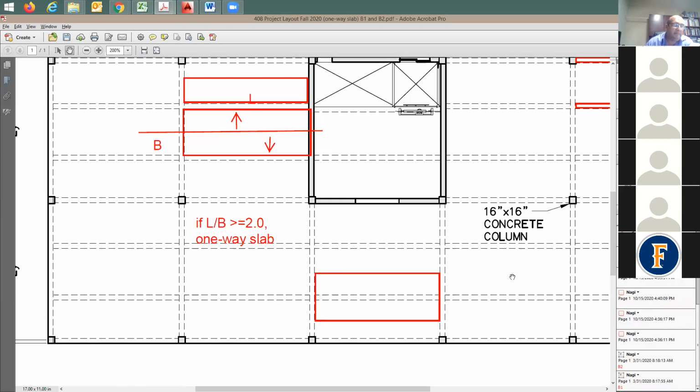If you'd like to design the beam and you need to figure out how much load goes to this beam, you need to find out the weight, as in dead load and live load that you guys have seen before, supported by this beam. Find out this area, multiply by the uniform load, to find out the total load supported by this beam. How about this girder here? Does it support any direct portion of this slab? I'm going to say no.